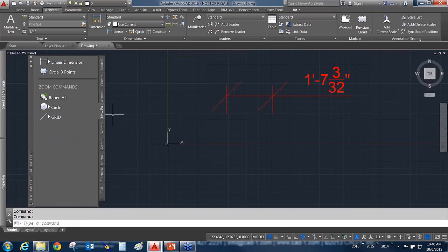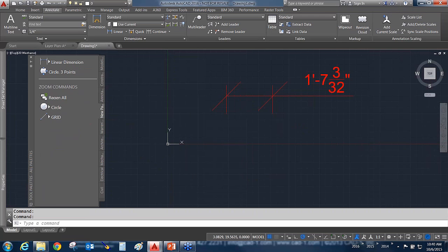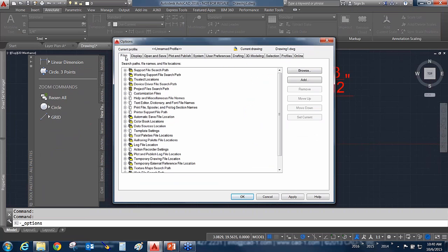Well, there's a couple of different ways to do this. You need to understand something about how AutoCAD works with tool palettes first. So let's take a quick dive into the AutoCAD options dialog box. For those of you in CAD management who aren't AutoCAD experts, you want to avert your eyes for a minute, because this is a pretty dangerous dialog box to be goofing around in. So don't go playing around in here. Inside here you have something called tool palette file locations, plural, locations.